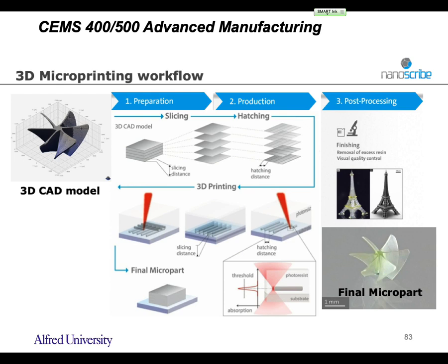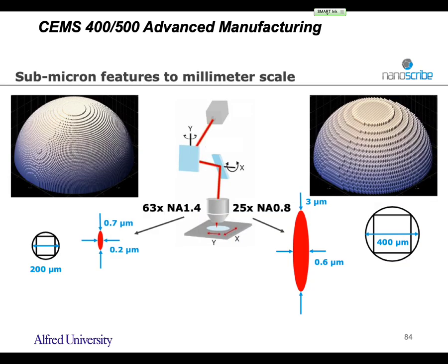It's a pulse laser, but you can still work on this stereolithography model. Right. So then of course you have to control the power to control the threshold, right, to get your final part. So the focal length of the objective lens, if focusing that laser, it matters a lot. It determines how fine your resolution is.